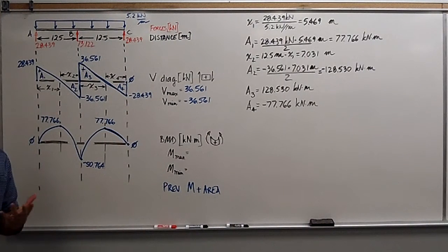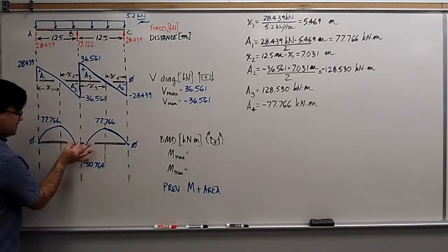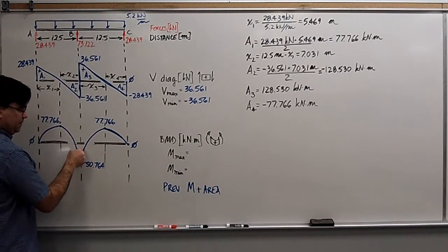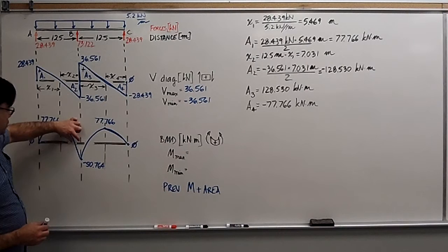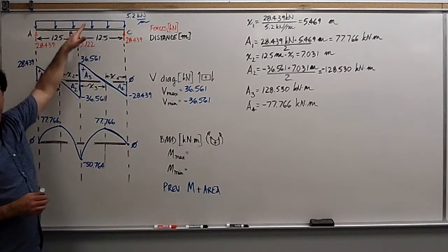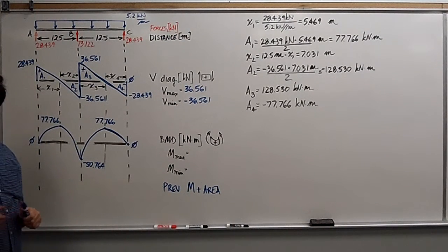Now here is another important thing. If I drew this bending moment diagram to scale, this distance here, where the bending moment diagram goes through 0, should match the distance of the inflection points you found previously in part 1 of this video. Okay? So give that a try, see if it works. We're ready to wrap it up.